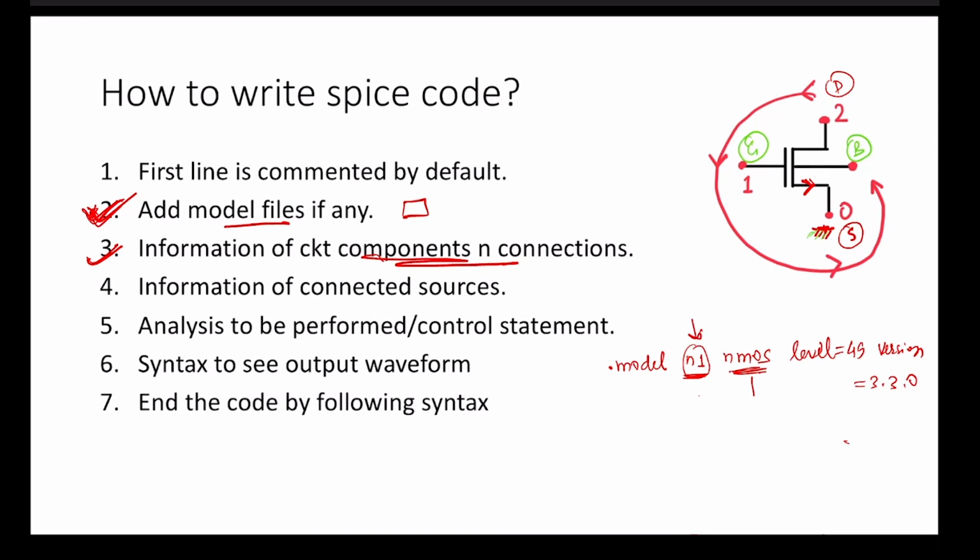Okay. So generally, what we do for NMOS, we connect the body to ground. And for PMOS, we connect the body to VDD. So to write code for this, how will we do that? I'll give you one example of how to write a Spice code for MOS.